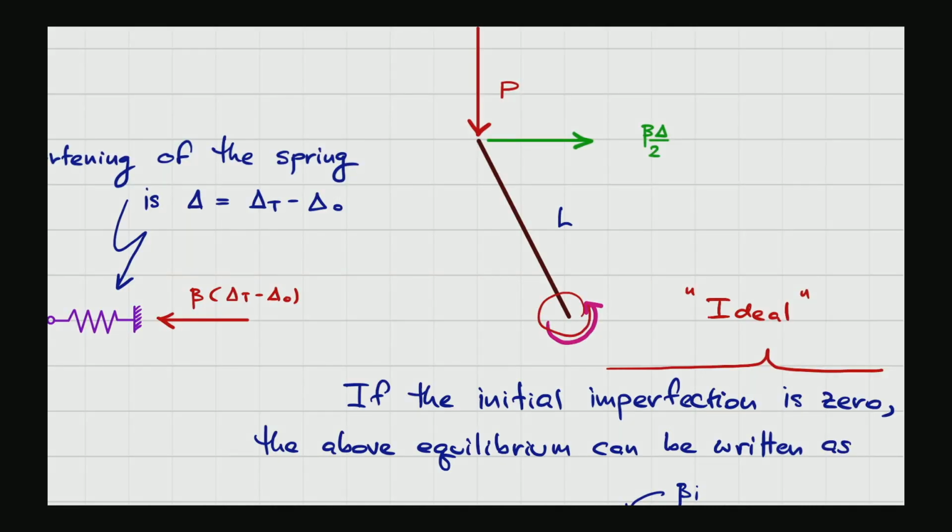You do not have the moment here as it is the fictitious hinge, so it is simply 0. As you might remember, this is the point we call the inflection point, so at the inflection point we do not have any bending moment. Without bending moment there, the internal moment is 0.